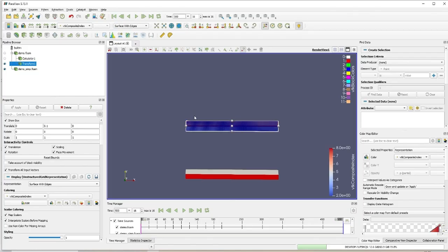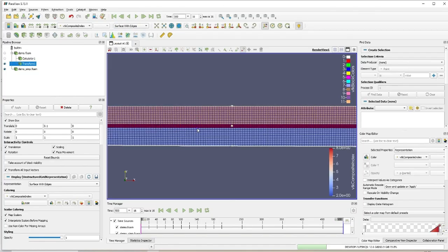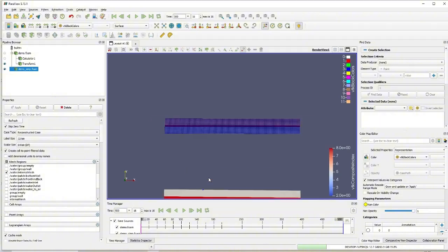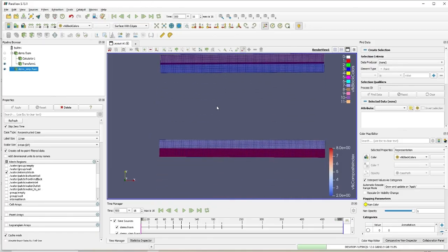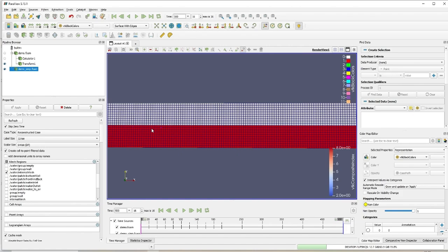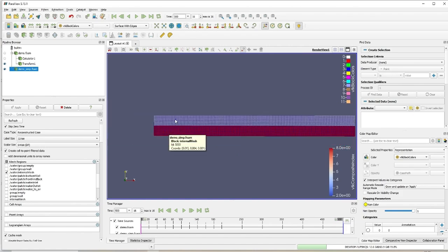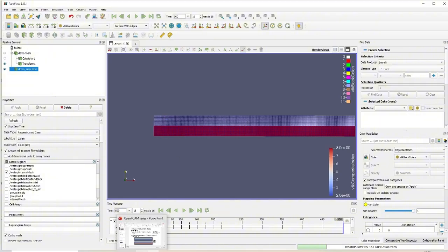If I show the mesh as well for the old mesh, we can definitely see the 3 regions of air, solid, and water. The solid is aluminum. But if we look here, that is the most recent one, and I also display the mesh. There's no solid existing, right? So that means we have eliminated the solid mesh, and only include the thermal conductivity between the interfaces. Okay, that's good for us.